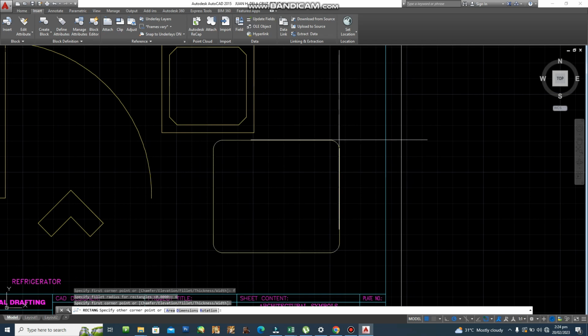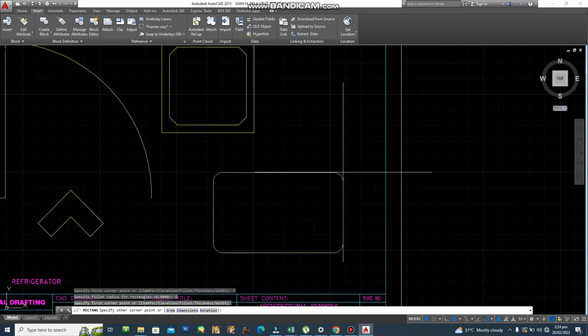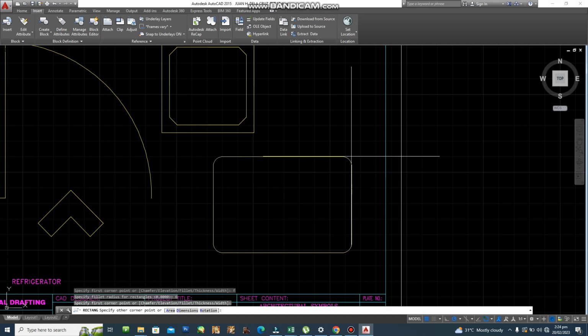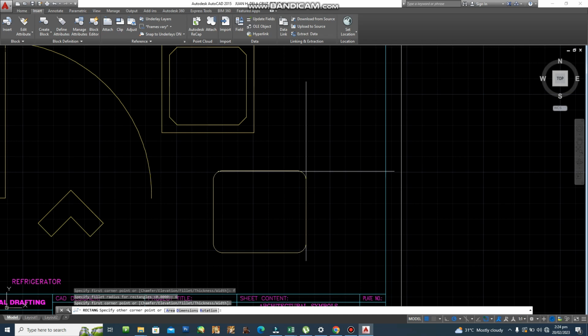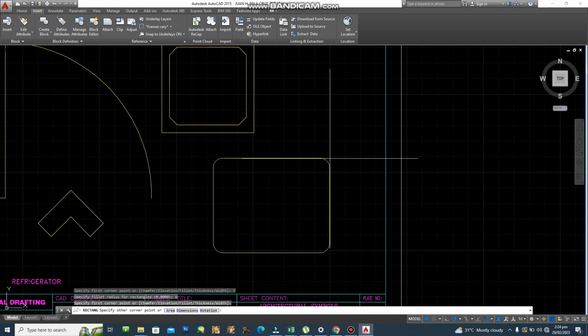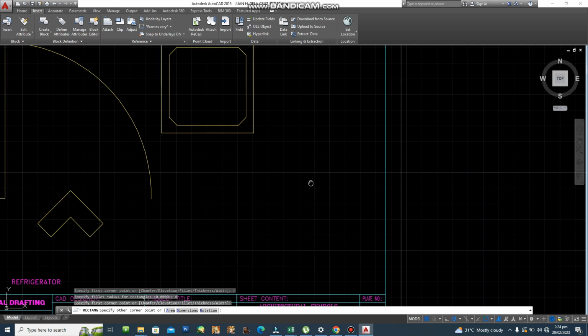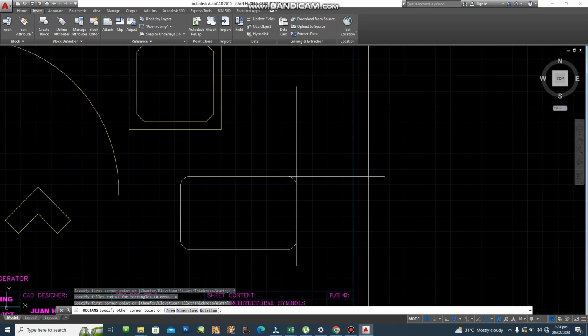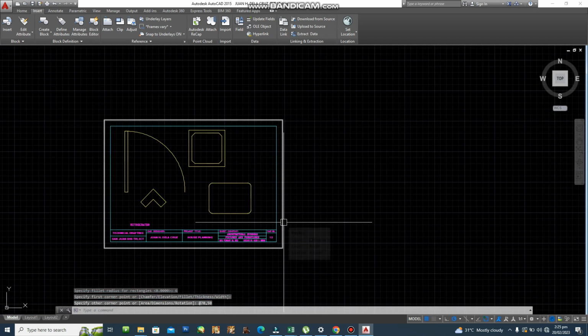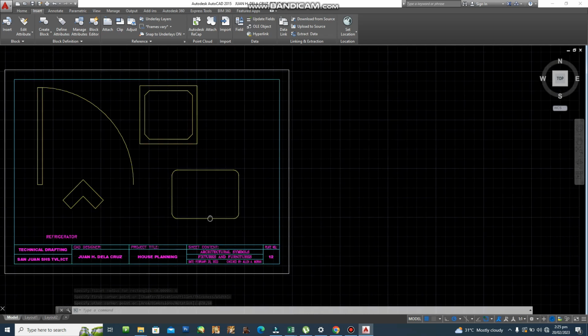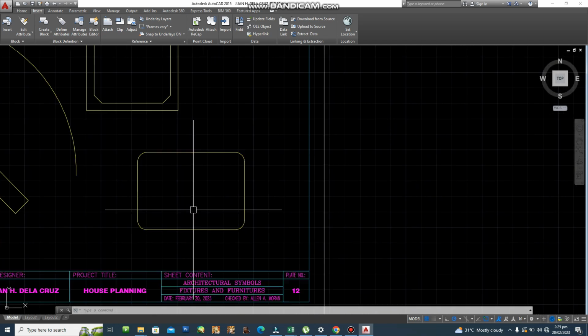As you can see, the rectangle is in fillet mode, and the specified radius is visible in the rectangle. For us to create the specific measurement for our L tab, we'll type the relative Cartesian for this one. So it will be at 70 is the length, comma, and then 50 is the width. Enter.